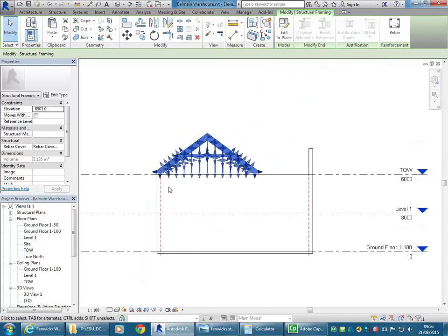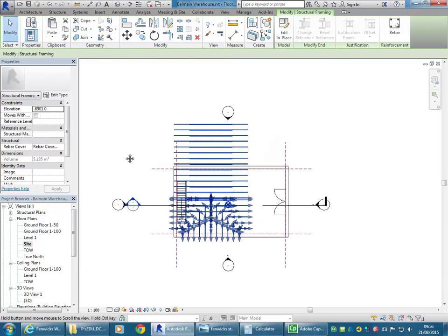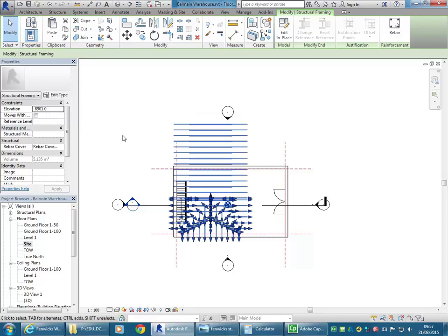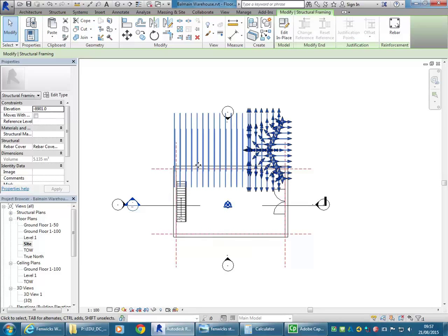after we rotate it. So if you go to the site plan, that's a useful one. You might not have used that very much either. In your floor plans, you'll have site, which should view from above. And so as long as you can see it above your building, then you can press space, and that will flip it. Space on your keyboard. Yeah, space bar. In your floor plans, you'll find site.